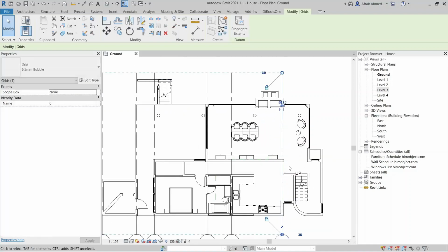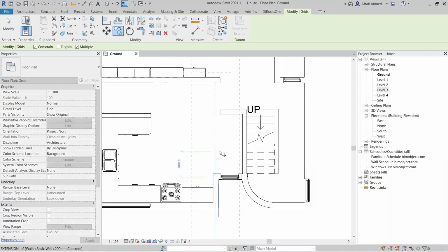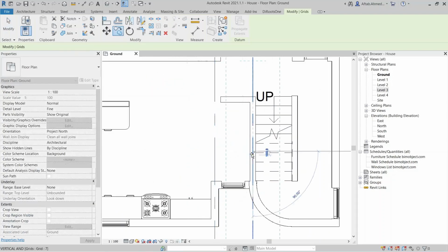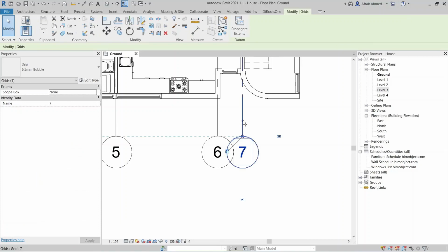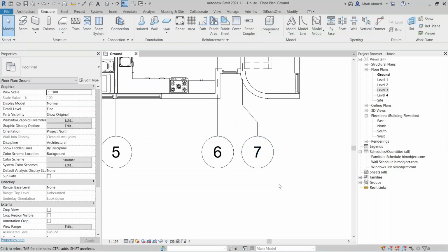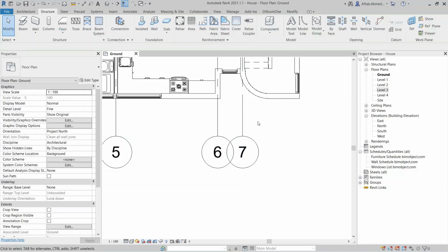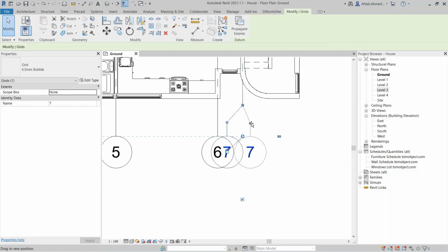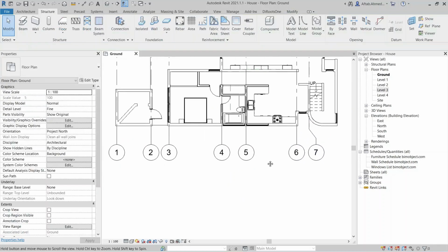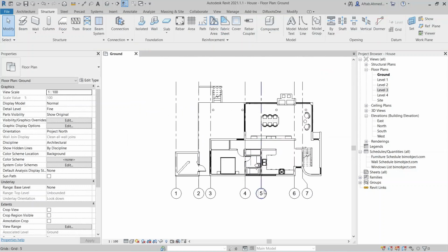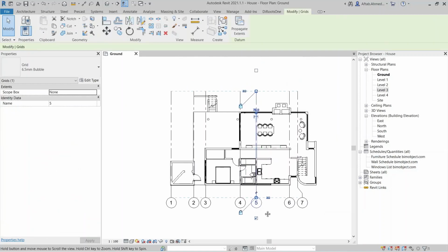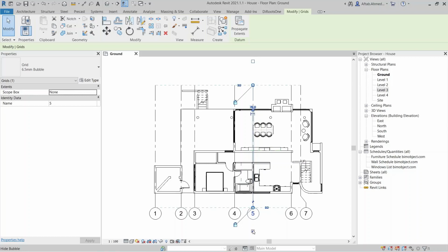If two grids are overlapping due to being too close, the grid bubbles can be adjusted by adding an elbow. To remove the elbow, simply drag the line to straighten it. The grid line will straighten. A visibility parameter has been added to the grid to display the bubbles on either side. You can show or hide the bubbles at any side.